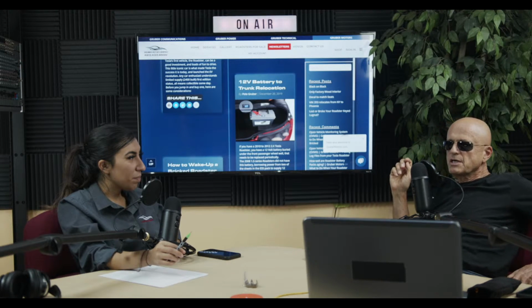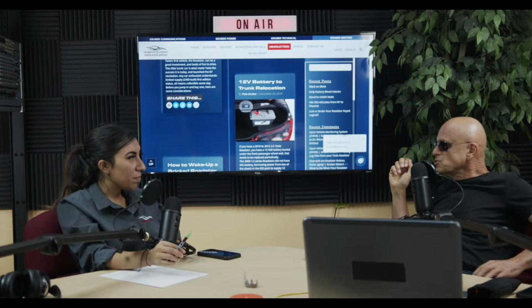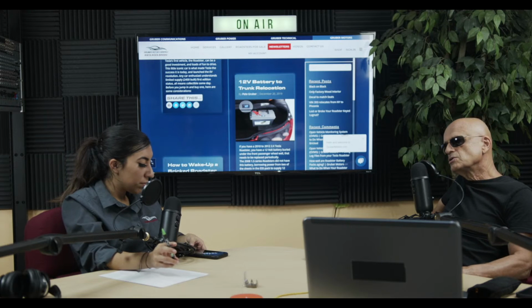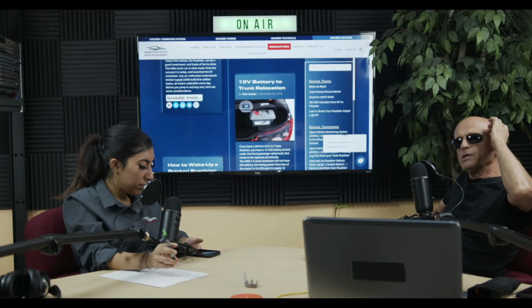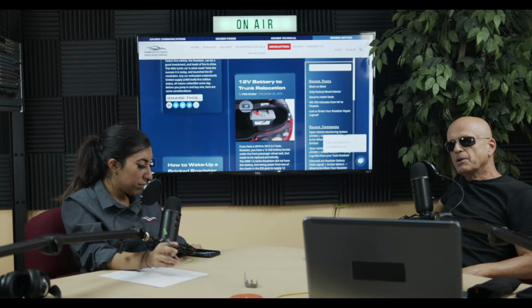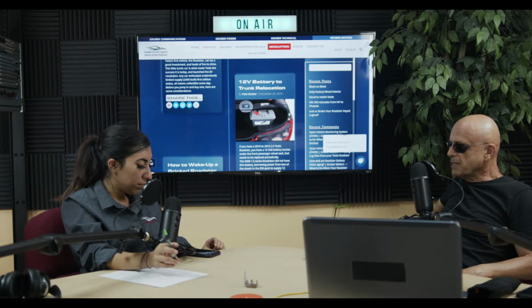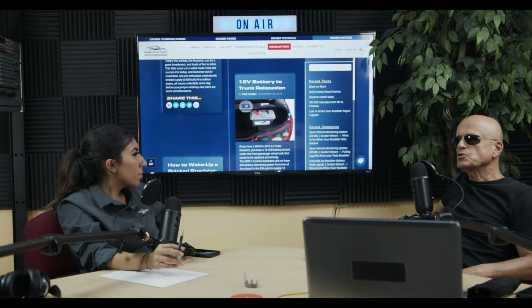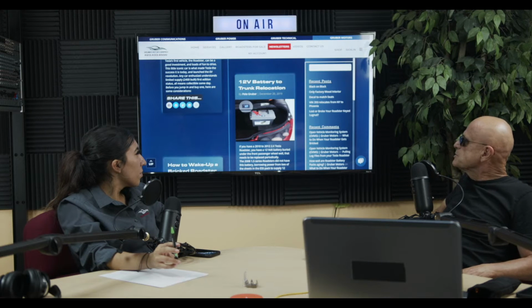What we came up with was a relocation for that battery. Essentially what we use is a small ammo box that gets mounted in the trunk of the car. We reroute all of the 12-volt feed wires to that box. We put a meter on the box so you can see what the condition of the battery is, and we upgrade the battery. Instead of a 12-volt 8-amp-hour battery, we put a 12-volt 12-amp-hour battery in it, and it is a UPS battery designed specifically for electronic applications like this, versus the deep discharge or deep starter battery that was originally in the Roadster. So that's what that newsletter describes: why we did it, the advantages of it, and how it works.